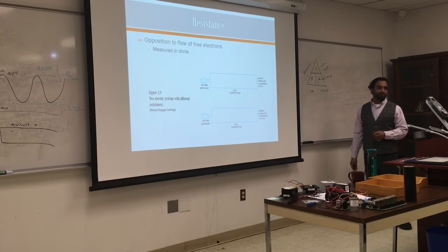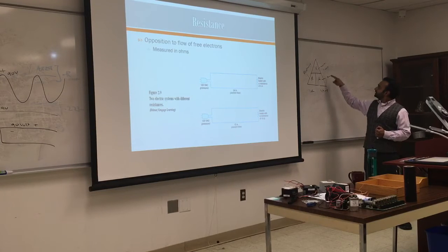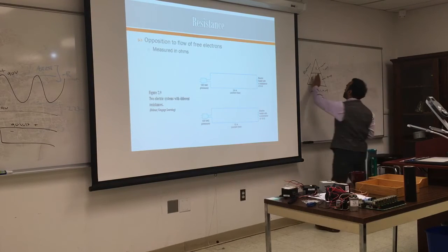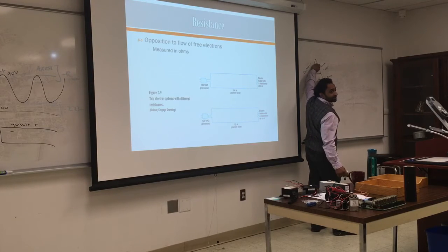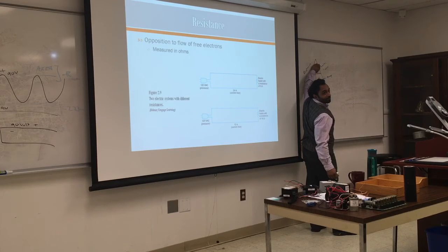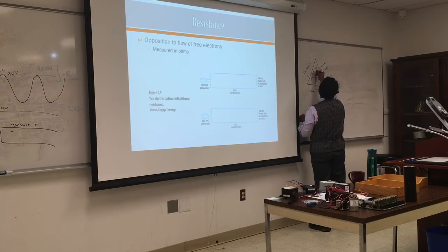What does that mean to us? We really care that much. If I want to find the amperage, I'm going to divide the voltage by the resistance. But the units have to be amps, volts, and ohms. If I want to find the resistance, I'll divide the volts over the amps. If I want to find the volts, no, multiply. So from top to bottom, you divide.